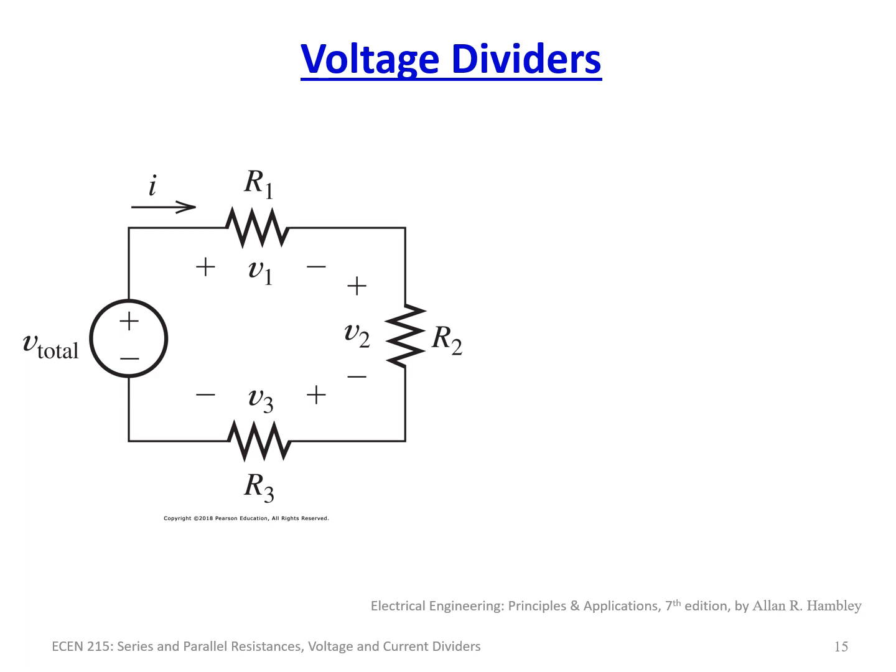So here we have three resistors. We have R1, R2, and R3. And we're now asking, what is the division of voltage across the three resistors? Now, a little fun fact here, V1 plus V2 plus V3 must equal V total. Remember Kirchhoff's voltage law. In a loop, the net sum of voltages must be equal to 0. So V total must equal V1 plus V2 plus V3.